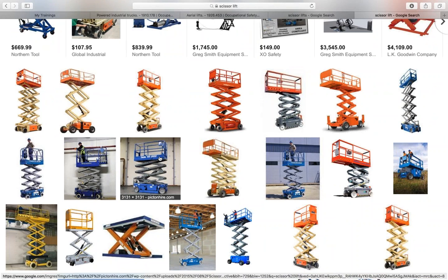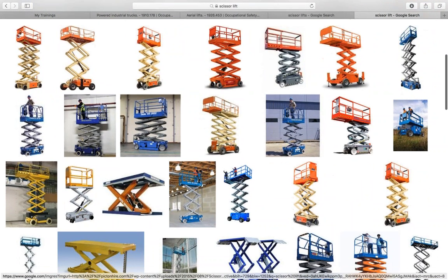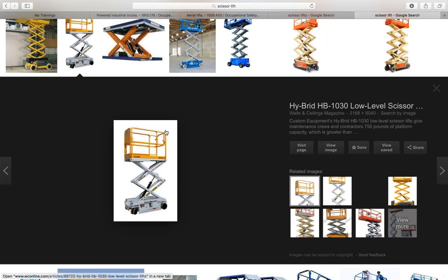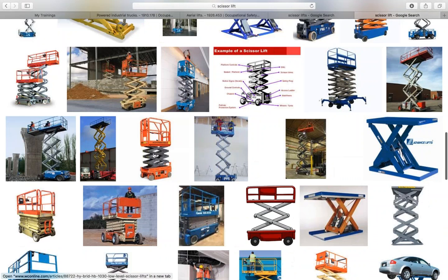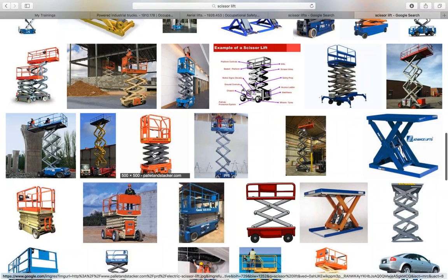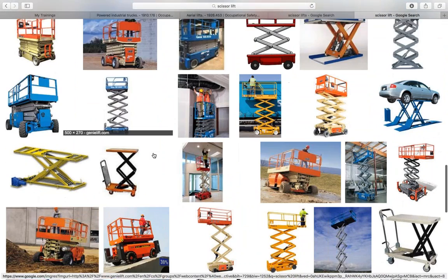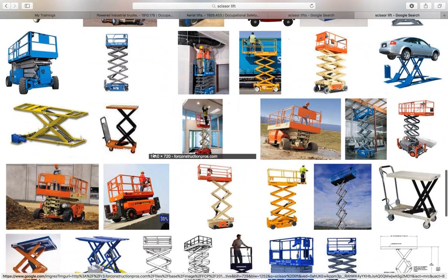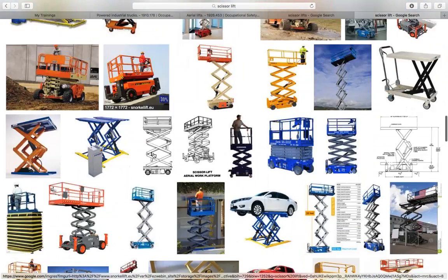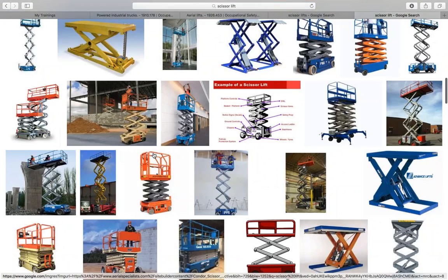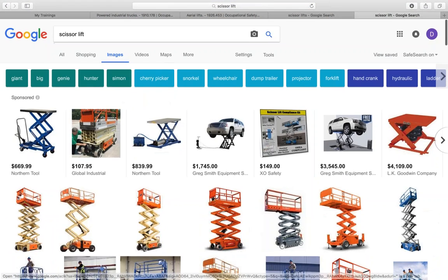And this is what I'm talking about. I'm just going to show you a quick picture. Here you go. Here's a scissor lift, and there's a gate. And instead of a gate, some of them only have two chains going along the backside. So be very cautious of it. Even though an employee has personal fall arrest on, you definitely want to be cautious of those ones with chains on them, and obviously always exercise caution.